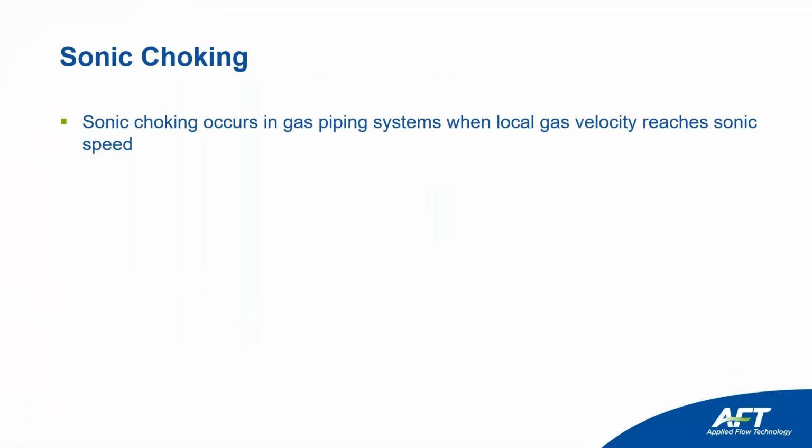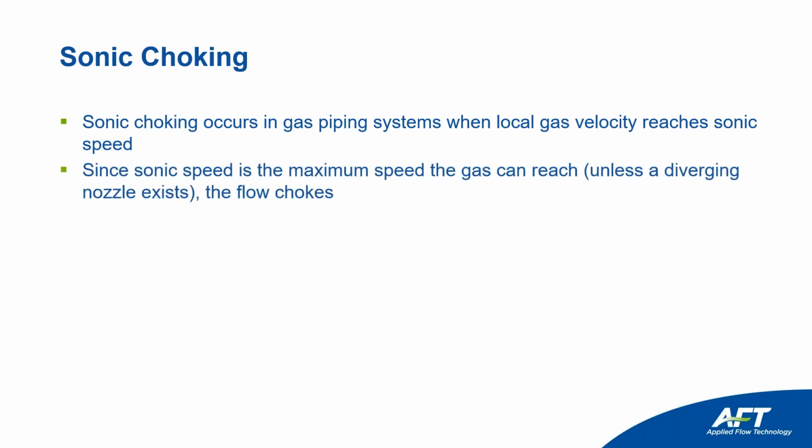Talking about sonic choking, it happens when the local gas velocity inside a piping system reaches sonic speed, or the speed of sound, or a Mach number of 1. And the Mach number of 1 is the maximum speed that the gas velocity can go.